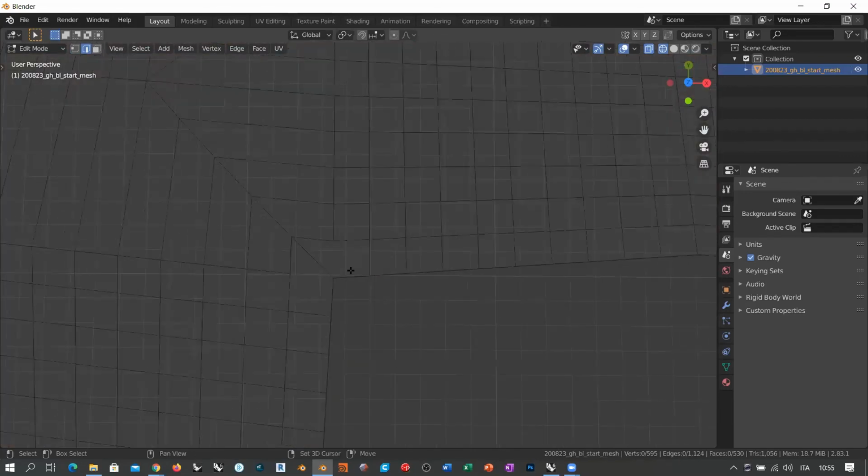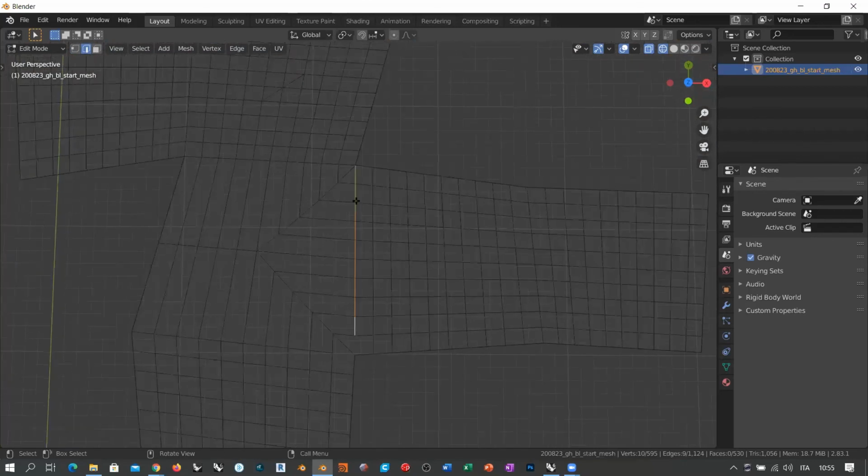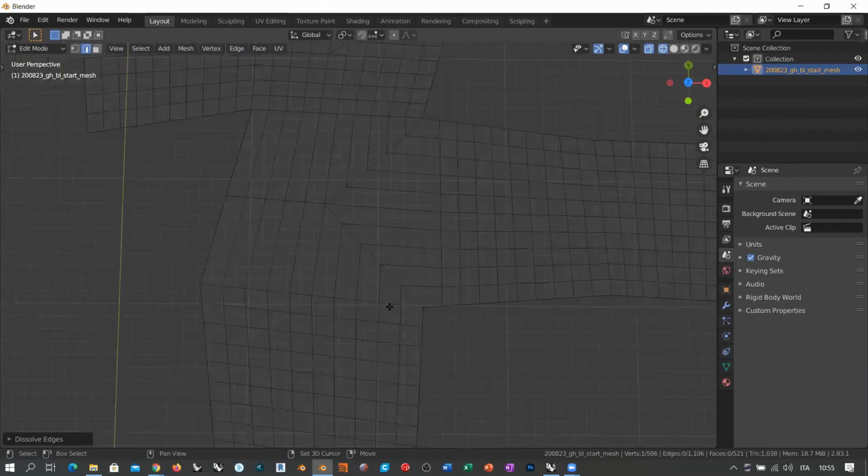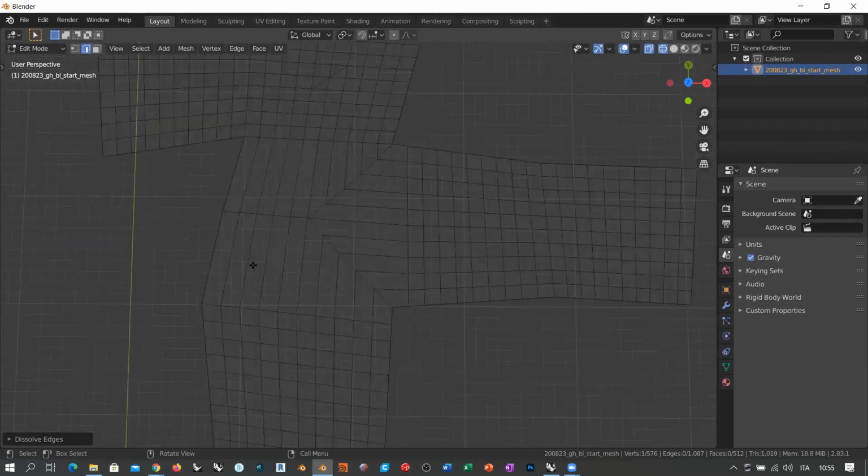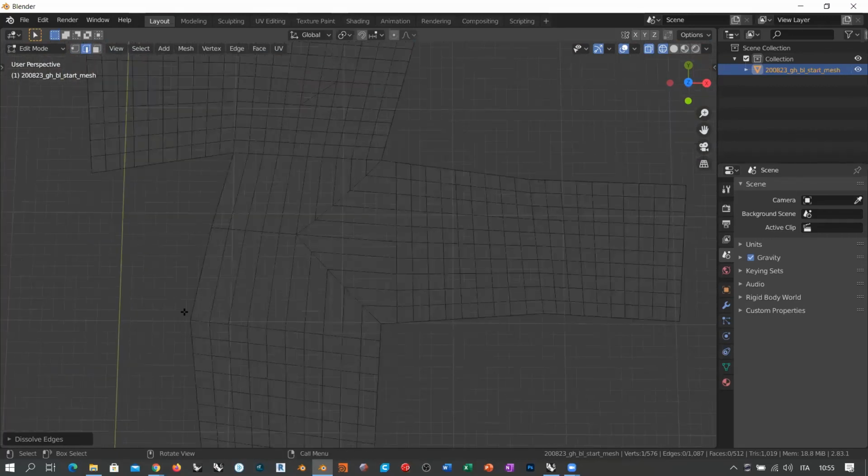Okay, so this is a problem because if I take this line of edges, right click and dissolve it, I start losing something along this edge. And also, if I select all this line of edges and dissolve it, I am starting to lose the original corner point. This is inevitable, okay? So this topological editing that we are doing is also deforming a little the general aspect of the mesh. While all this editing inside this area didn't change the outline of the mesh, dissolving the edges that converge into a vertex or a corner is actually changing the topology, the shape.